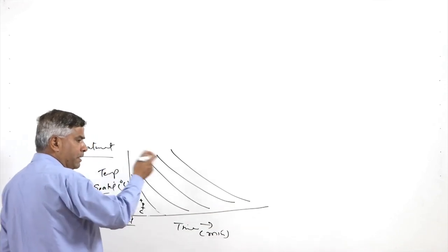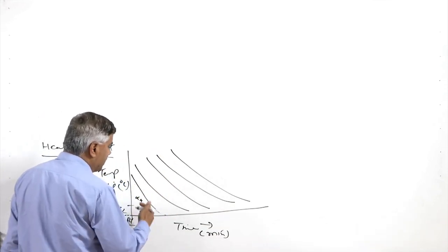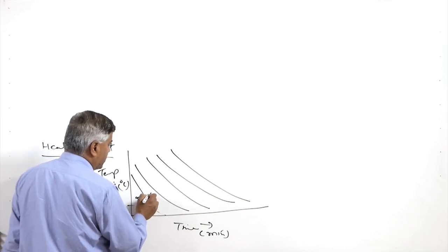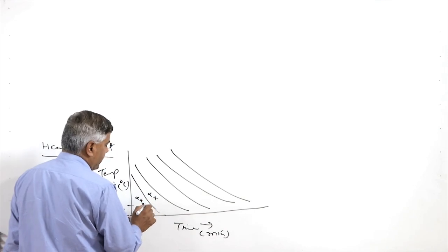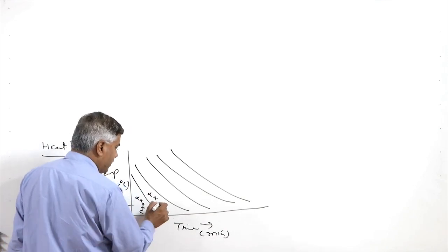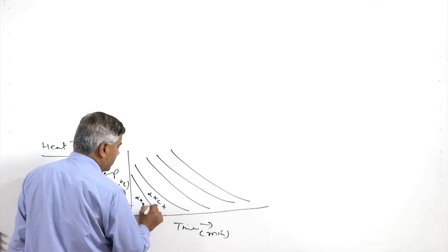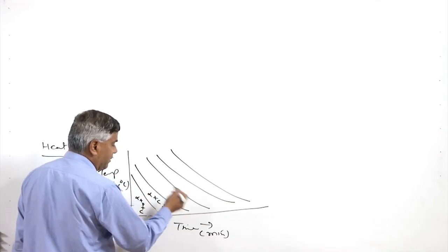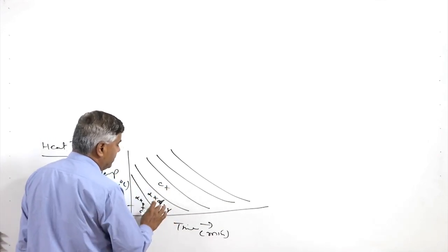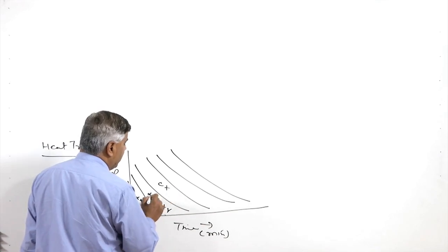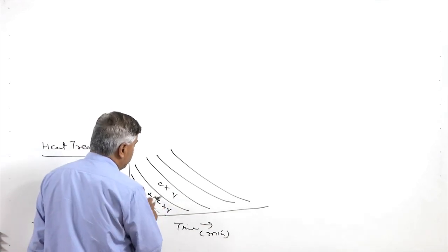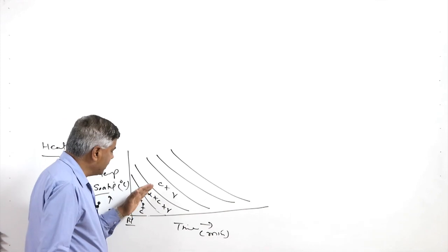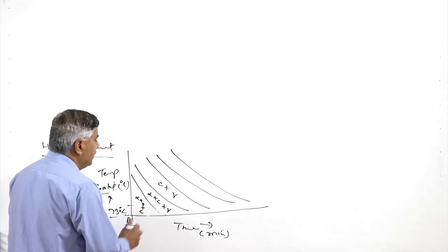When it is exposed above the upper critical temperature limit, it starts getting decomposed. So, first of all the pearlite decomposes into the austenite. So, it first retains the ferrite and the cementite, plus pearlite gets converted into the austenite. Thereafter, it is the turn of the ferrite to convert into the austenite. So, carbide will remain stable, and alpha will also convert into the austenite. So, now the ferrite and the pearlite have converted into the austenite, only the carbides are left.